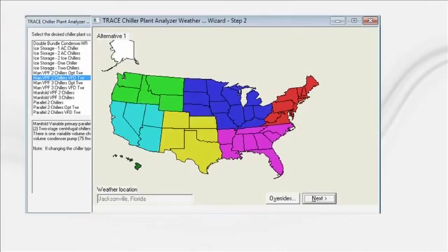We'll use the same project as Charlie. In this case, it's 2 chillers in a variable primary flow system. The chillers are in parallel, and the cooling tower fans have variable speed drives. Next, we select Jacksonville, Florida as our location. By the way, there are worldwide locations available too. Charlie had an office building with no economizer at a design capacity of 710 tons.